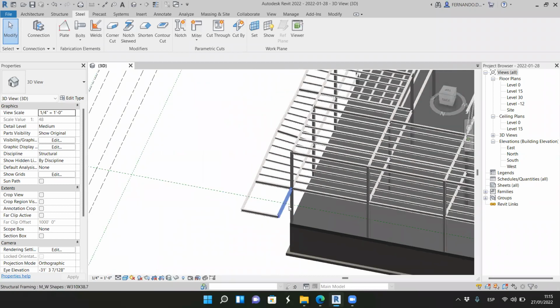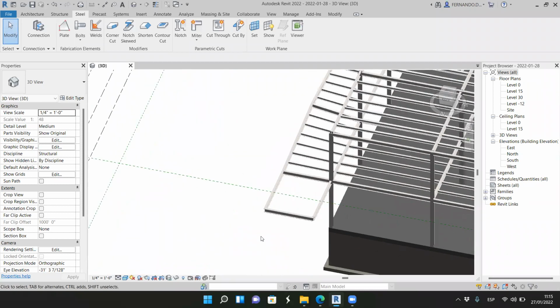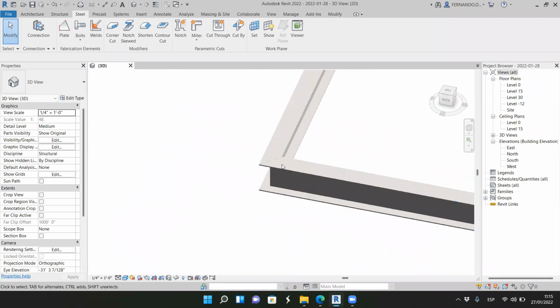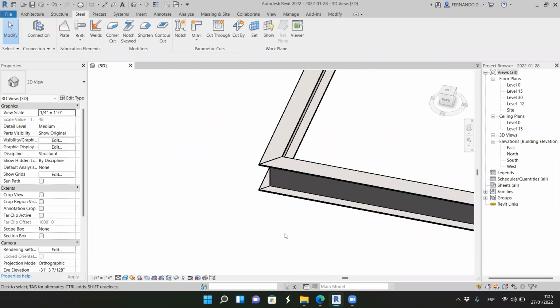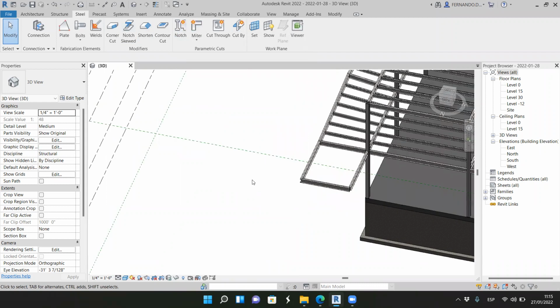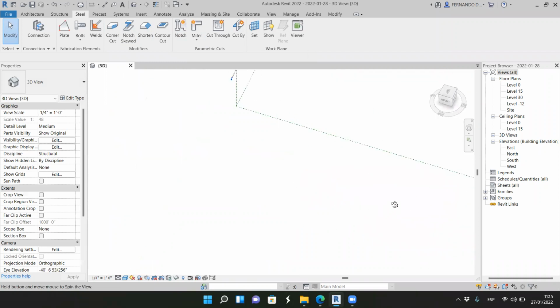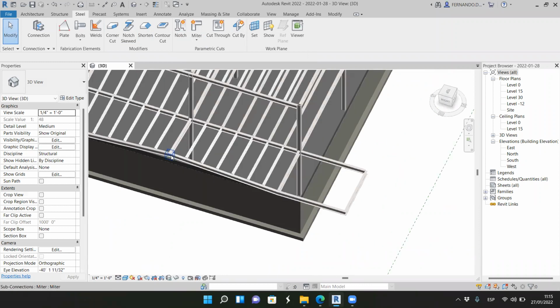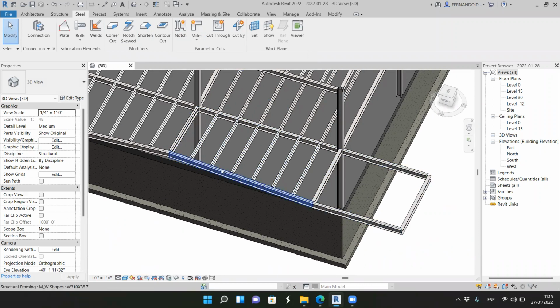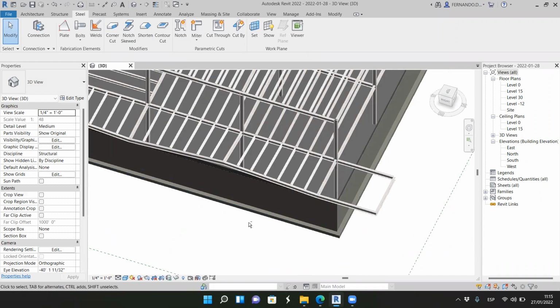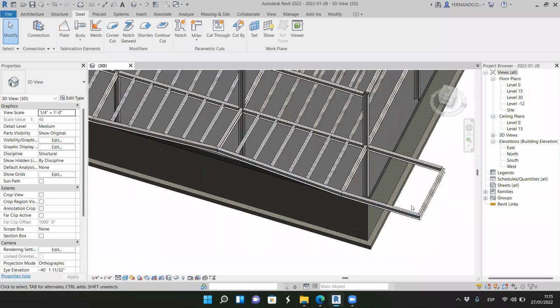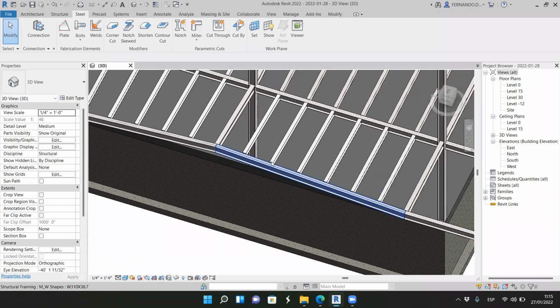Okay, what's next? When we have an exposed steel structure, we should be careful with this, and we have two wonderful tools, miter and notch. But now, if we have a complicated shape like that and we want to cover this with roofing material, we can't use a roof by default in Revit. It wouldn't work if we have this tilted beam here and this is horizontal.